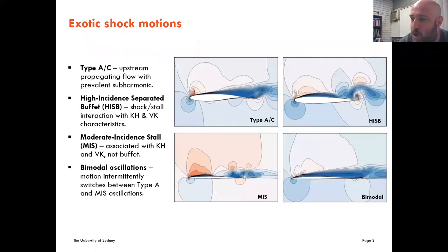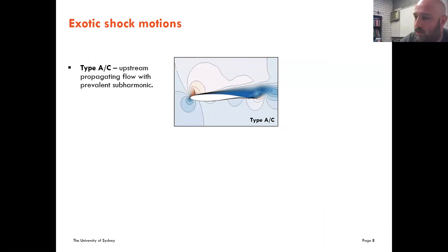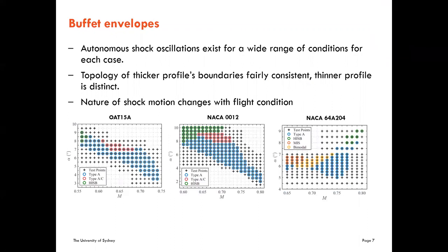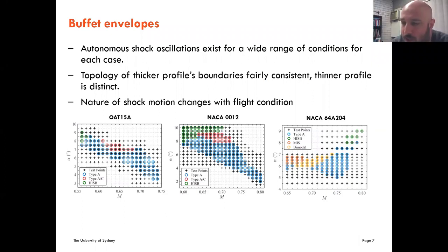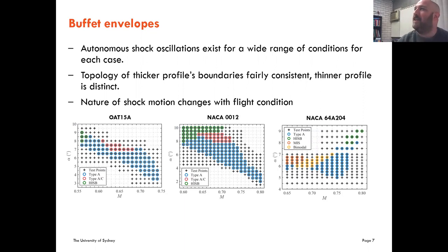It becomes a little bit blurry. And you can get it all the way up to around 0.8. Yeah, okay. That at least we've seen with this aerofoil. But this behavior is very aerofoil dependent. Yeah, that's true. Usually I have seen in literature it's around Mach 0.7 to 0.85 or 0.82 that they carry out this kind of experiments. Yes, there's a sweet spot where almost every solver will give a buffet, even though it's probably wrong.